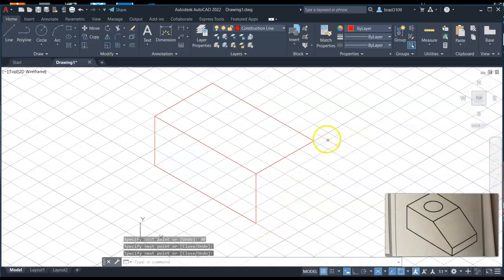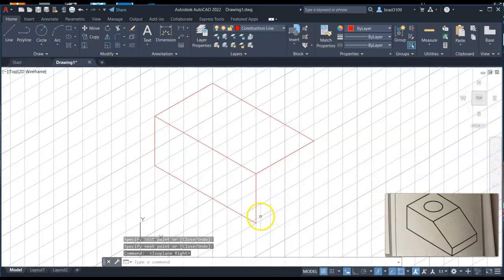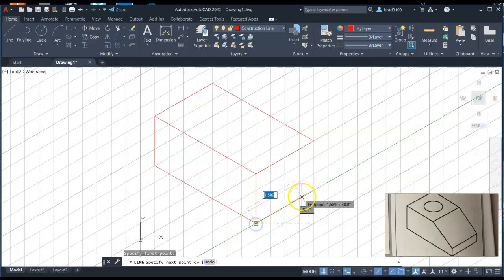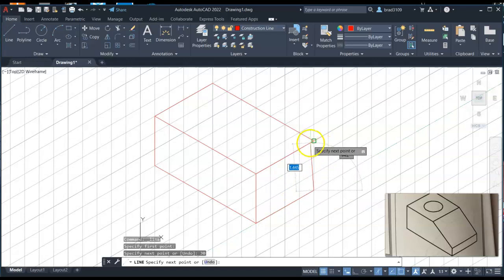Now, we are going to do the same thing. So as we construct this isometric view, we're just changing back and forth. So let's go ahead and put it in the right isoplane. You can see how our box lines up. So let's go ahead and draw this now. So this was a 2, tab 30, and we can go right on up. That's going to be 1.5 at 90. Right click and enter. So now I have those construction lines there as well.